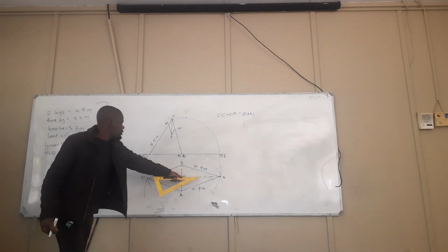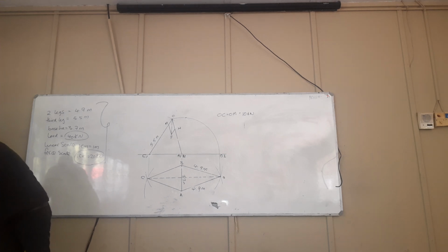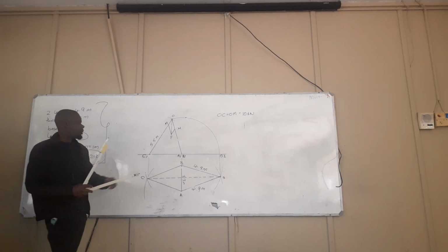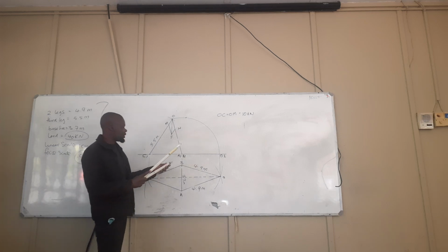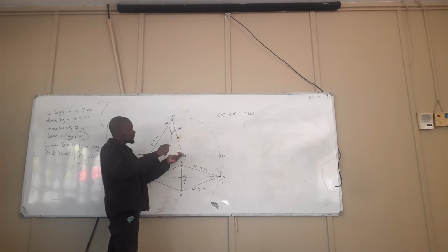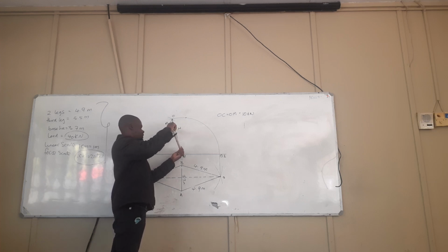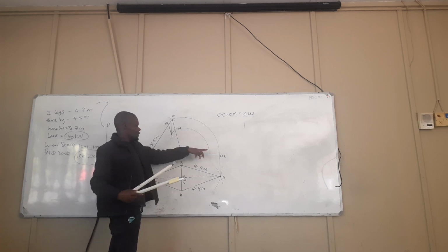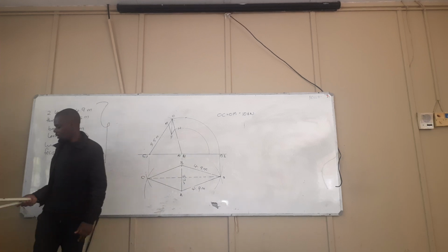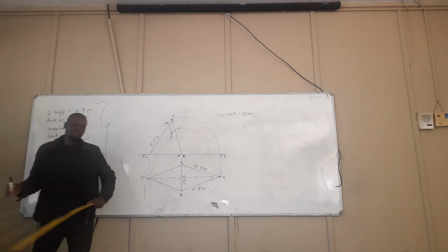Now, what about these two legs? With those two legs, I would like you to transfer point N downward. So with this center and this radius, go down until it cuts the horizontal line. When it does that, please drop that point. You can call that point N1.